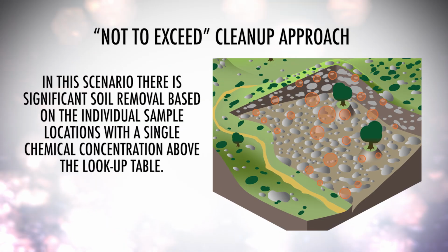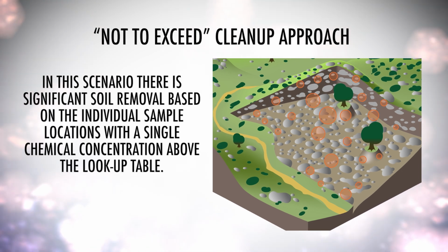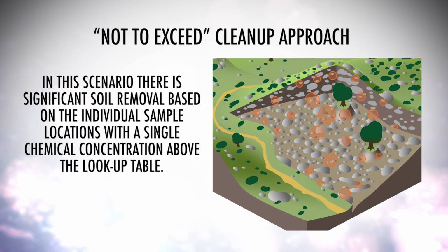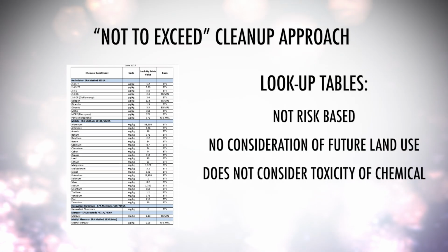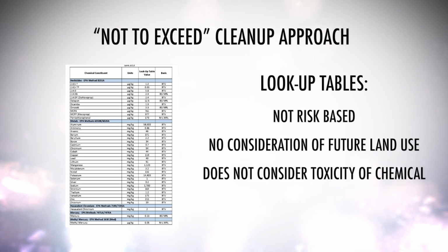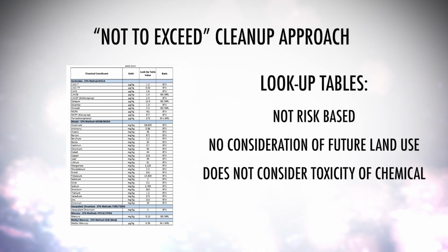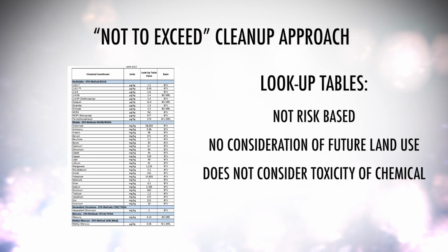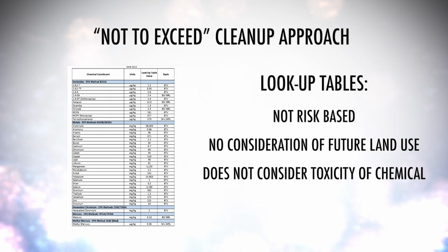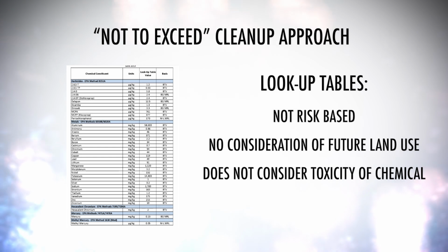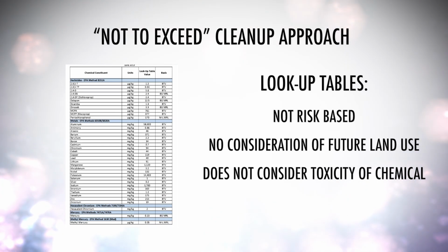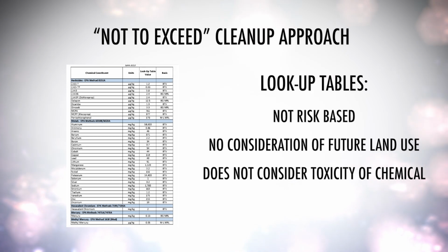In this scenario, there is significant soil removal based on the individual sample locations with a single chemical concentration above the lookup table. Remember, for this cleanup to background levels, the lookup table values are not risk-based values, so there is no consideration given to the future land use, exposure frequency, exposure duration, or even the toxicity of the chemical. There are lookup table values for more than 130 chemicals. If a single chemical exceeds the lookup table, soil removal is required.